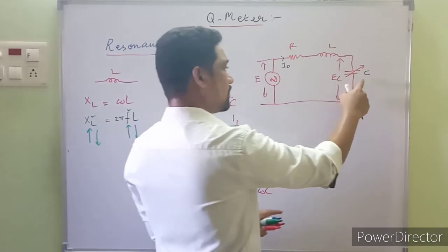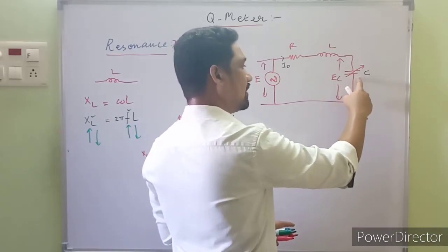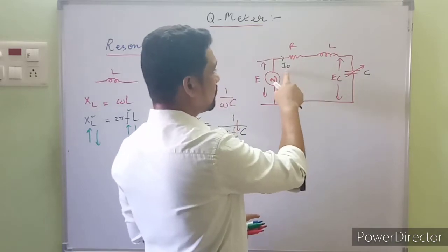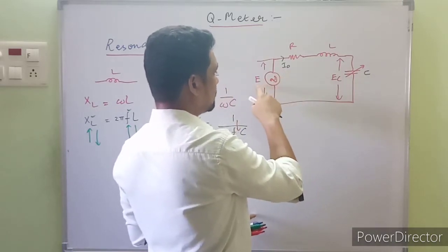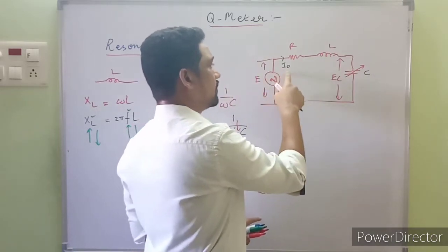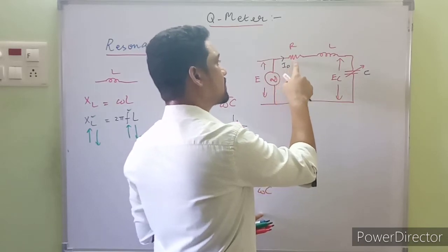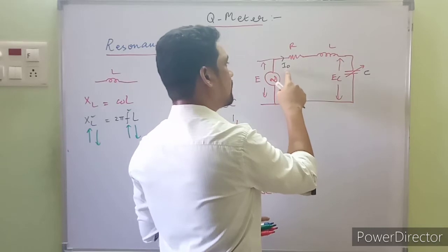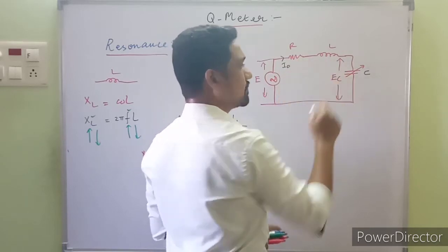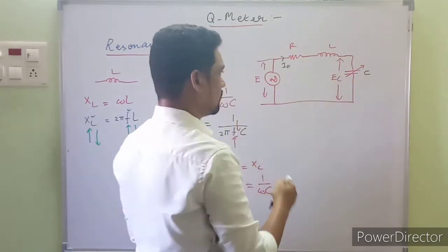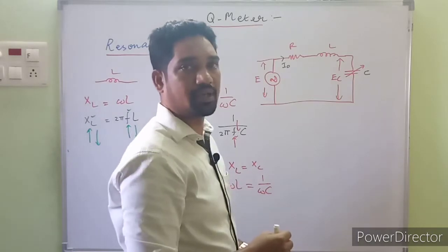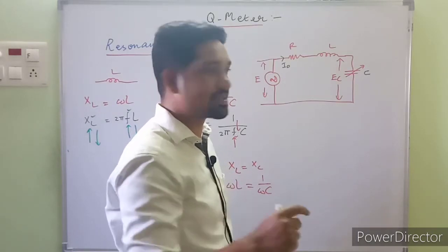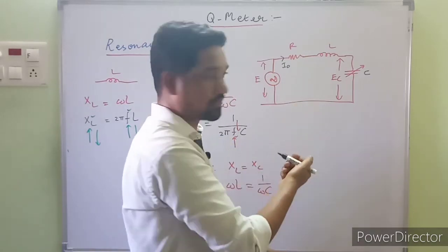By varying, let's suppose, the value of the capacitor, we have achieved the resonance, and under resonance I naught will be flowing. The source giving rise to I naught, the same I naught will be flowing through the resistor, all these components being in series, I naught will be flowing through this and this and this, right? So having knowledge of the phasor diagram will be more convenient to understand what happens actually in the circuit, right?